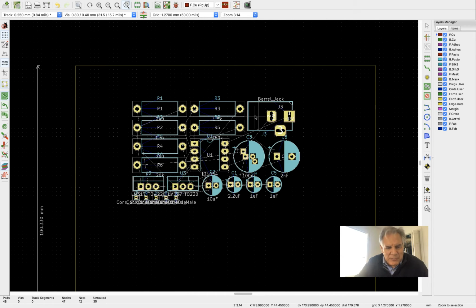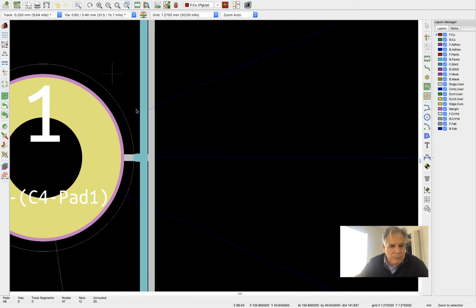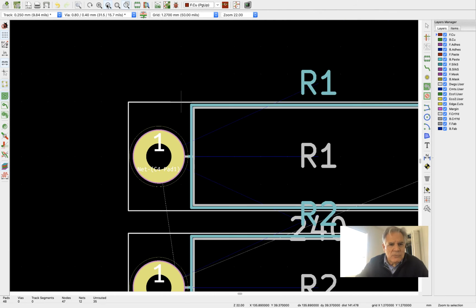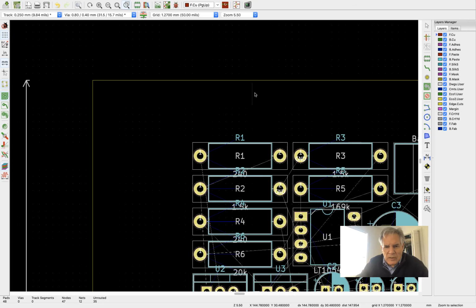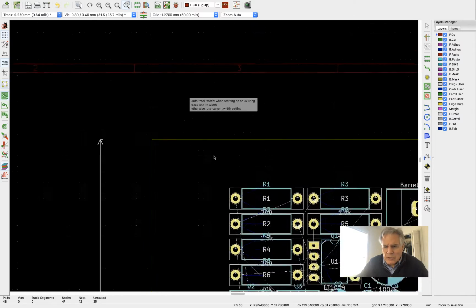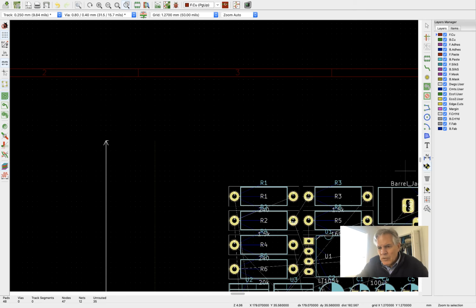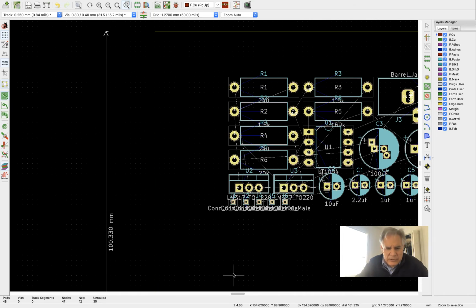We want to play around with this, and the thing that we obviously want to do is explore the locality of parts to see what parts are naturally next to each other and make the simplest connections possible. Some of these resistors, I see R2 and R3 are connected here. They probably want to be together. Whoop, did not mean to do that. We will zoom back out. And there we go. I think you can also zoom sometimes with your mouse pad, and we can use these sliders to put us where we want to be.